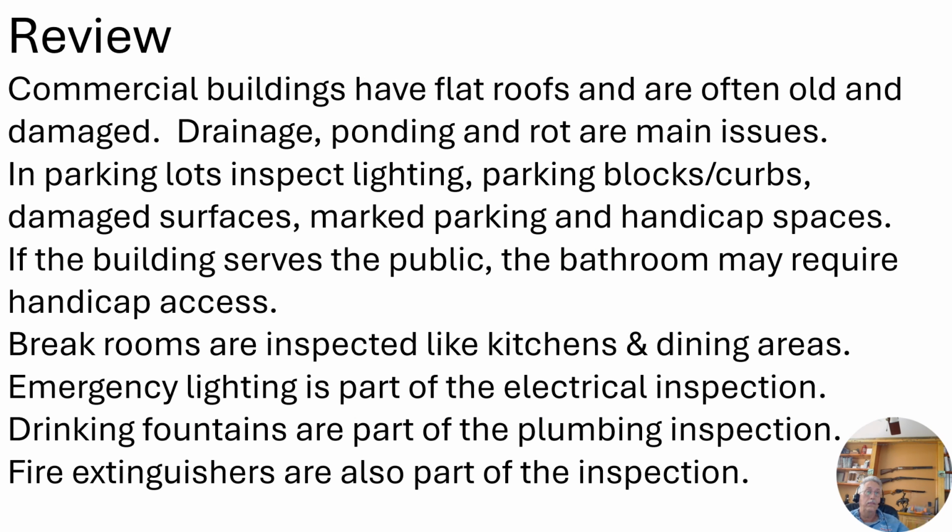All right, let's review. Commercial buildings a lot of times have flat roofs, and often those flat roofs are old and damaged. The biggest issues are draining and ponding, rot, parking lots. If it has lighting, that's part of your inspection. The parking blocks or curbs should be inspected, whether they're there or not. Sometimes they're damaged. Check for potholes, just like you would in a driveway. Marked parking, like handicap spaces.